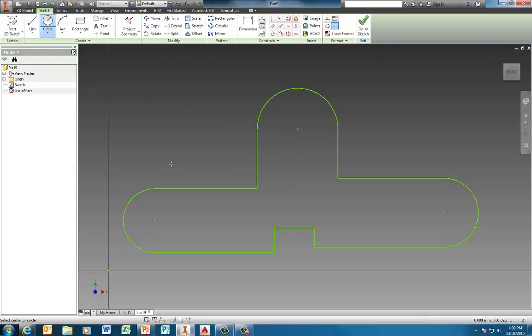I can now apply a circle, and I'll just draw a circle in here. So we can snap circles to existing center points, which will make those 2 points coincident. One of the other options we've got, as well as making center points coincident, which we can do here, so coincident point to point, we've also got the concentric constraint. The concentric constraint works really well when you're dealing with radiuses, large radiuses, and arcs, because it's not necessarily easy to find or select the center point that's involved. So I've now got those on.